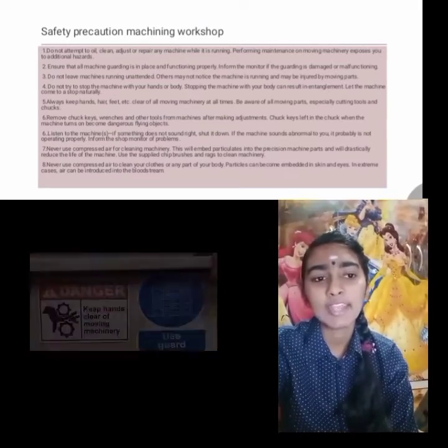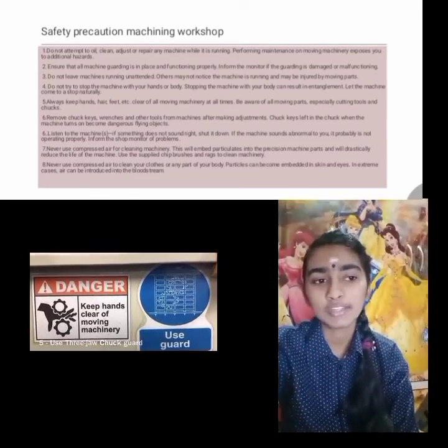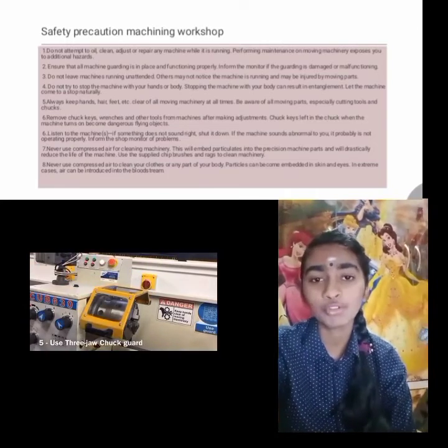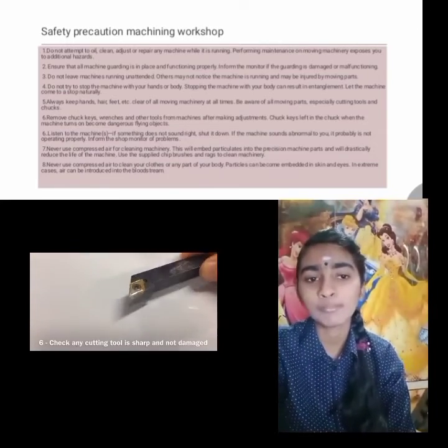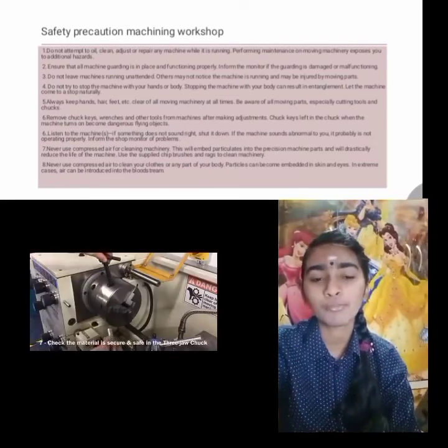Listen to the machines. If something does not sound right, shut it down. If the machine sounds abnormal to you, it probably is not operating properly. Inform the shop monitor of problems.